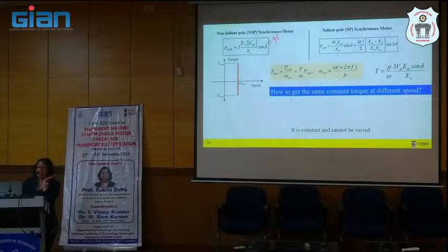And speed depends on your frequency. It is always synchronous speed, so speed is your frequency. If I want to change the speed in a synchronous machine, I have to change frequency, right? And that's what you do with your inverter. You're changing your frequency to get different speed.